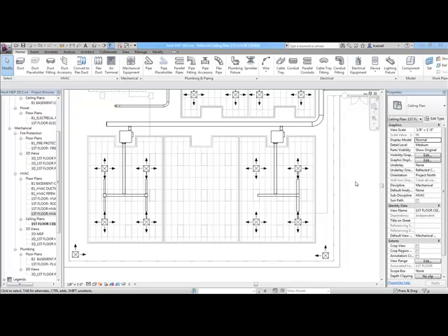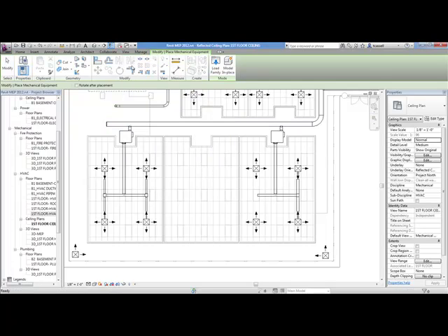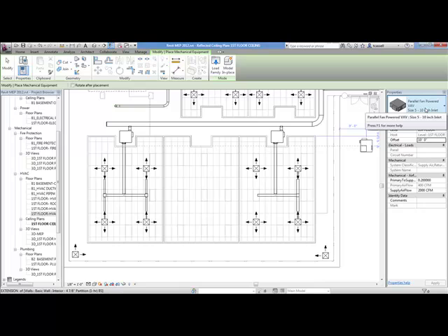Okay, now that we have talked a little bit about what Revit can do and how it works, let's focus on the actual drafting aspects of it and how it'll work laying out an HVAC system and laying out duct. You'll see that in 2D view it's not much different than AutoCAD. It's actually much quicker though. So in AutoCAD you do things like place blocks, or in other CAD systems you'll place blocks. In Revit you just place equipment.